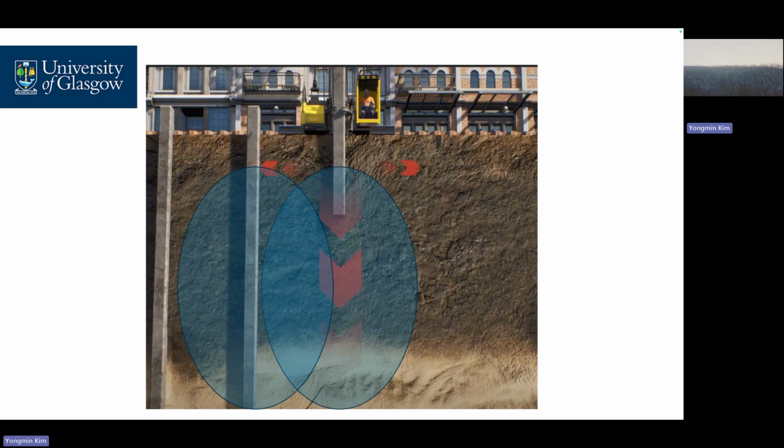Observe my hand. When we have sand material around here, it will be densified, right? Under dynamic force, the soil particles move and the porosity keeps decreasing due to the impact force.